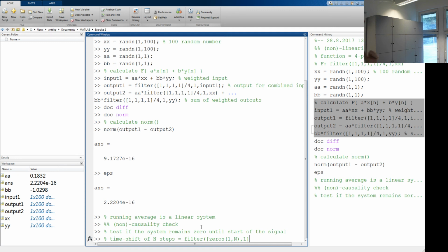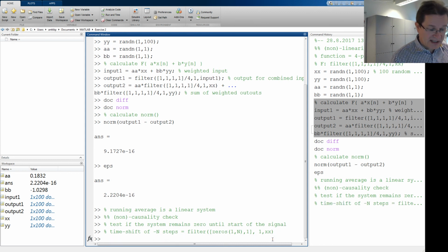Okay, that's time shift, negative time shift. So this is delay. Positive time shift, which means advance operation, plus m. You need to first reverse the order of this data, and then actually do the time shift, and then reverse the order again.